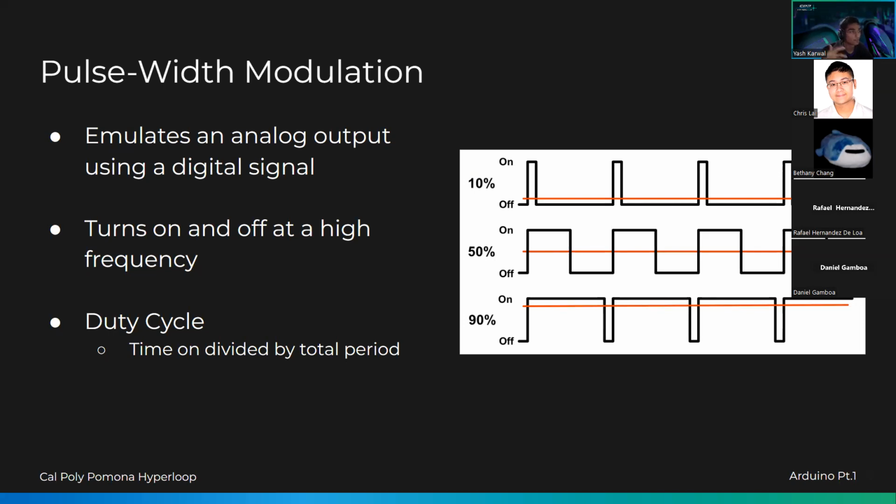You use the PWM signal to turn that LED off and on at a different rate, a different frequency, so that it looks as if it's dim when it's actually turning on and off at full brightness, just really fast.